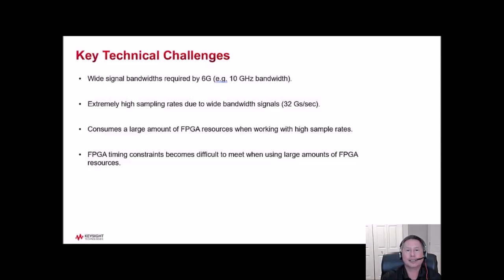There were several key technical challenges encountered when creating the testbed receiver equalizer demo. The first technical challenge is the extremely wide bandwidth signal, on the order of 10 GHz of bandwidth. This leads to the second technical challenge, where large signal bandwidths will require extremely high digitizer sampling rates. As the sampling rate increases, the hardware resources needed to handle the high sample rates increase considerably.